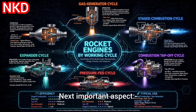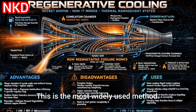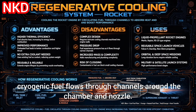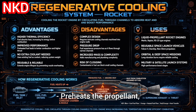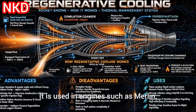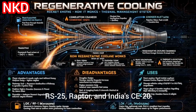Next important aspect: rocket engine cooling systems. A. Regenerative cooling. This is the most widely used method. Before entering the combustion chamber, cryogenic fuel flows through channels around the chamber and nozzle. This process absorbs heat, prevents melting, preheats the propellant, improves efficiency, supports engine reuse. It is used in engines such as Merlin, RS-25, Raptor, and India's CE-20.